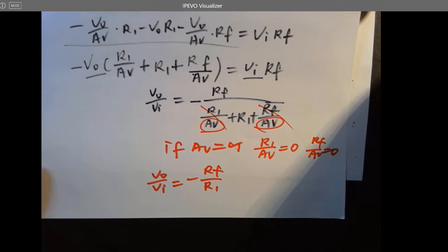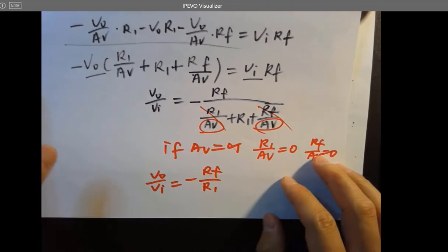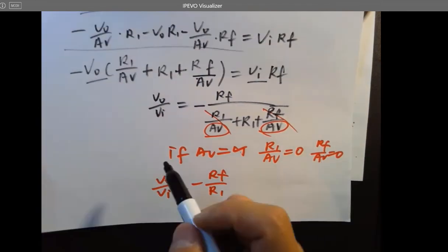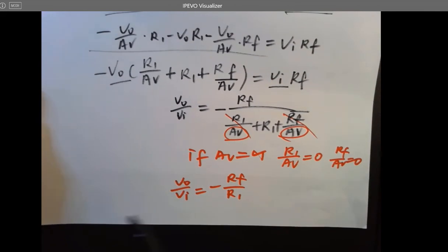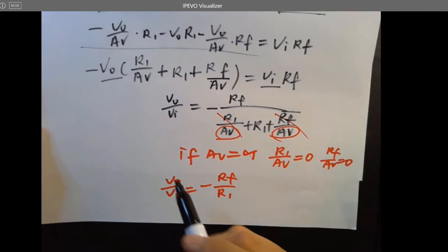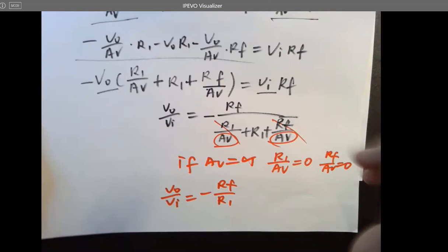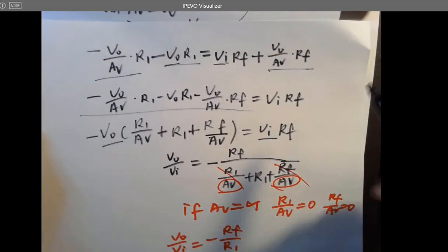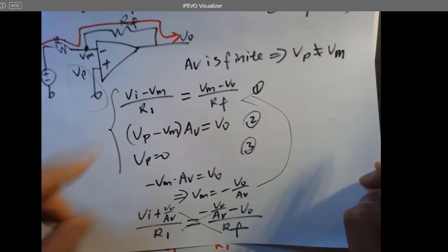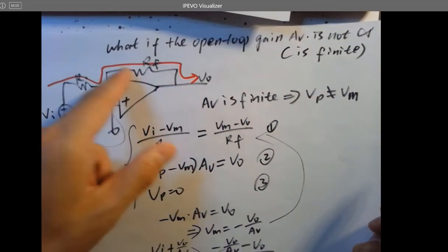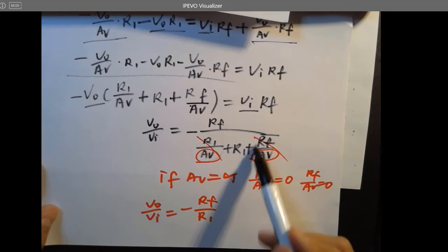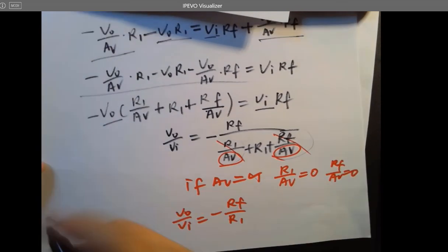Okay. So that's why you do need an ideal or something close to ideal op-amps to be used for application. So you have a pretty accurate, you can get a more accurate closed loop gain whenever you connect the circuit like this. Otherwise, it's introducing these errors to the circuit, right?